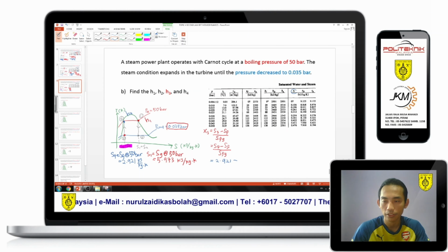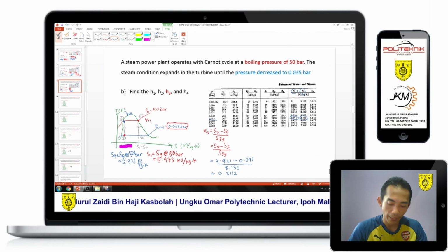Sf at 0.035 bar is 0.391, divided by Sfg, which is 8.130. So, X3 equals 0.3112.